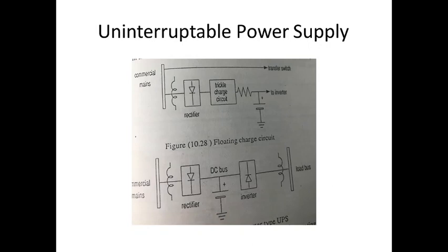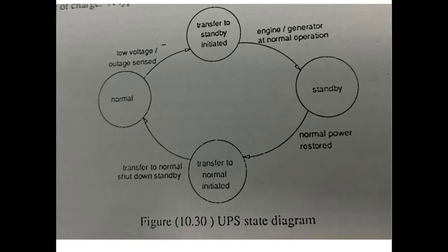The main disadvantage of the rectifier inverter design is the need for a rectifier at high power levels. The rectifier translates into both the cost of semiconductors and the cost of power lost in the rectifier. And there is no clear rule or guideline on which design is preferred. Now we will see the transfer mechanism of UPS.